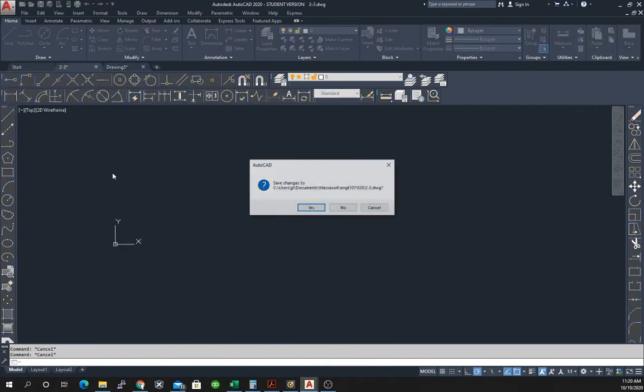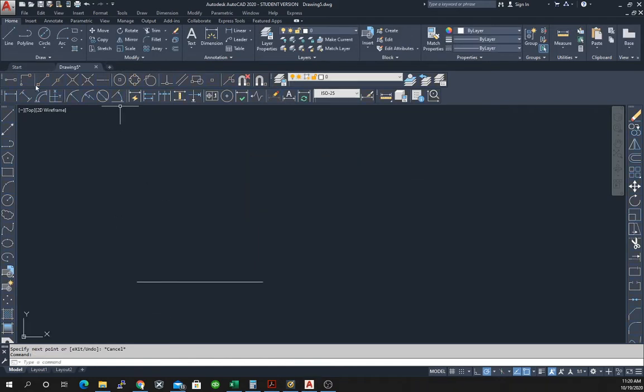And I'm just going to drop that drawing out of the way. We select this. We click on the center. Remember, if you click on the end, you're going to either do a stretch or a lengthen. Clicking on the center will start by doing a move, but then if you type C, enter, that move becomes a copy.